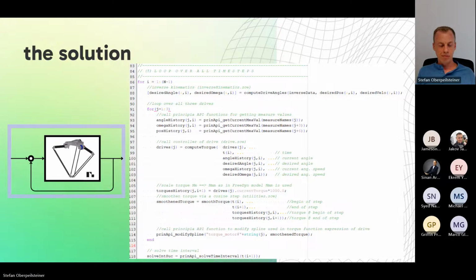So one has to define an update rate, or an interval, a small interval. Usually for the PLC controls, it's 1 millisecond, like in the real case. We've also chosen this one here. So compute the next 1 millisecond. And after this 1 millisecond, compute or evaluate the control law again, and then drive your system.